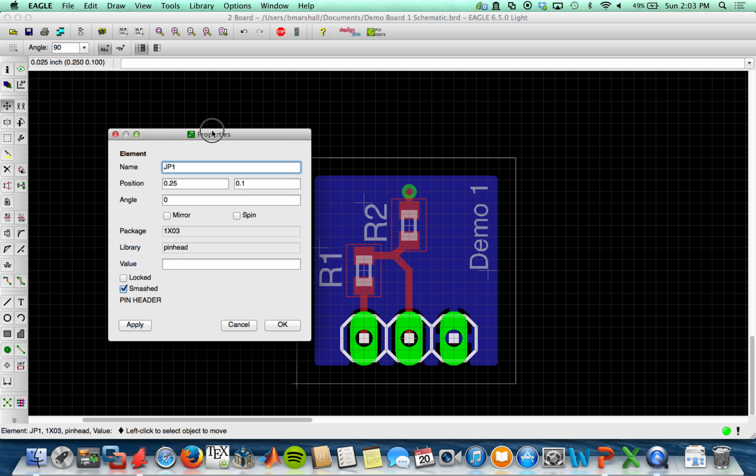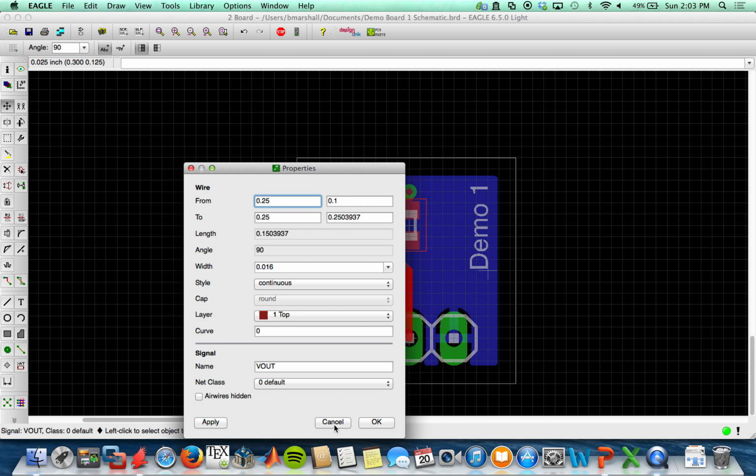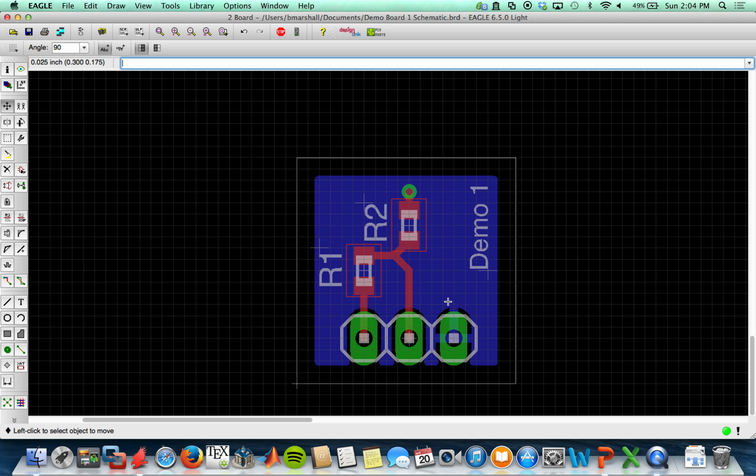Normally it's right in here. I'm not sure why it's not showing up. We can discuss that in a different video. But you can see the thermal here is this T that's created with the copper. Thermals are recommended for soldering unless you're doing high frequency RF or high speed digital stuff.